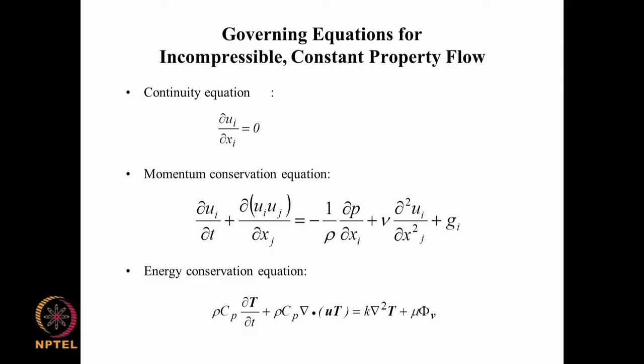Okay. So, that gives the strength of argument for the goodness of a CFD solution, whereas if we have to make any assumption about creeping flow or developed flow and all that, then we need to have very low velocities in the case of creeping flow and very long ducts of the same cross section in the case of fully developed flow. Those things are not found in practice, and so those assumptions are defeating when you want to apply to a practical case, but we do not have that limitation with CFD.